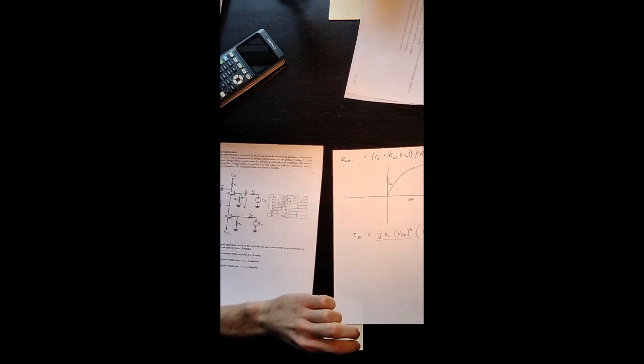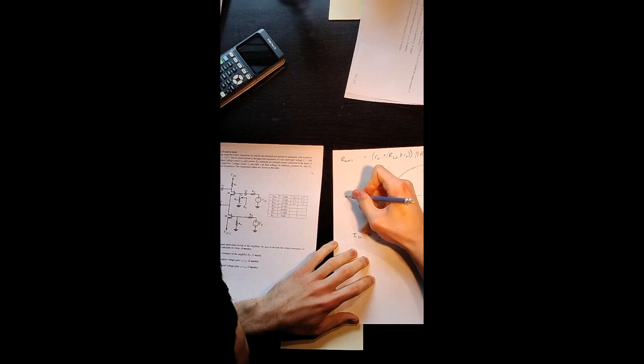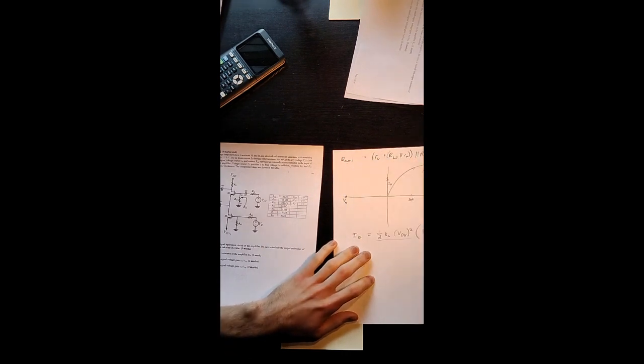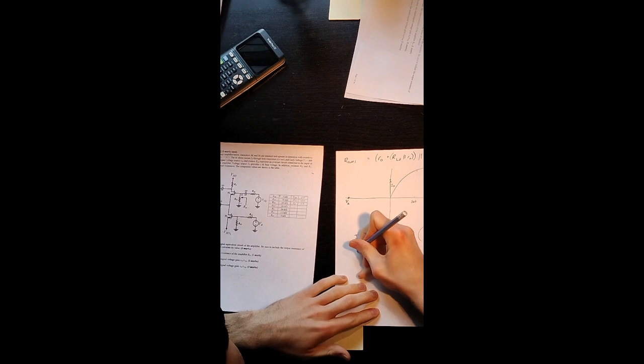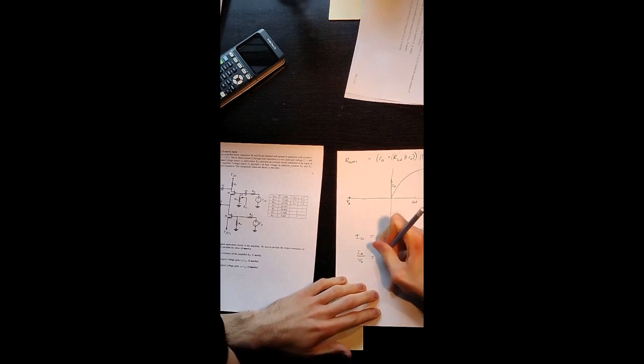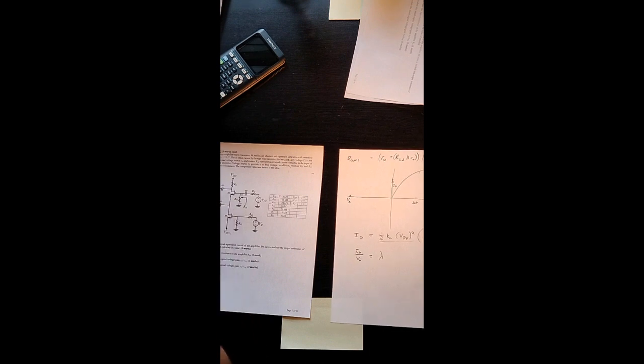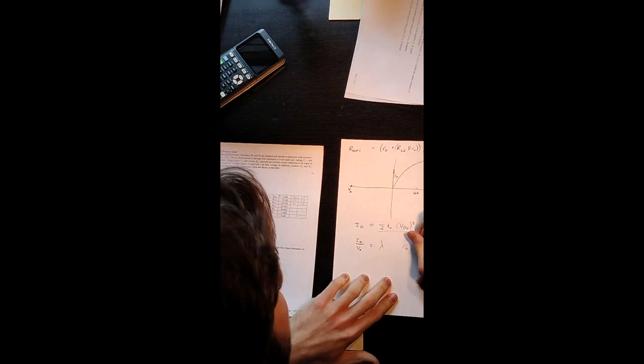Then, this voltage here is VA. And that depends only on the make of the transistor. So, if you wanted the slope of this line, what you could do is you could say just rise over run. It's ID over VA. So, and that's equal to lambda. That's equal to your slope. If you wanted your output resistance, therefore, you could say it's equal to VA over ID.